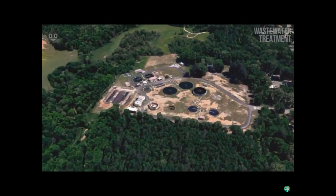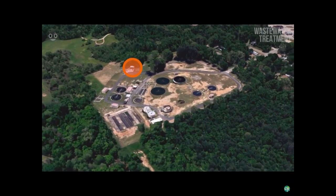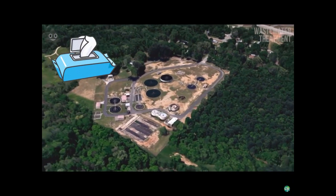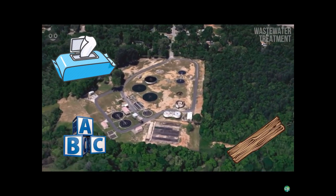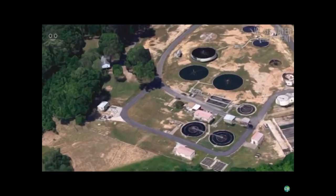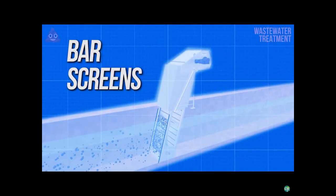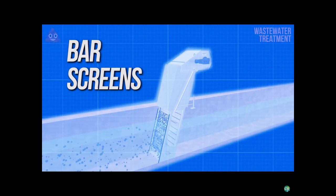That brings us to the first step of the process that handles larger items and sewage, things like flushable wipes, 2x4s, toys, or even guns. You name it, and it's probably been caught in a bar screen. Bar screens are exactly what you would think. They are large vertical bars that stand at the inlet of nearly every wastewater treatment plant, designed to stop larger items from getting to the plant and hurting machinery like pumps.